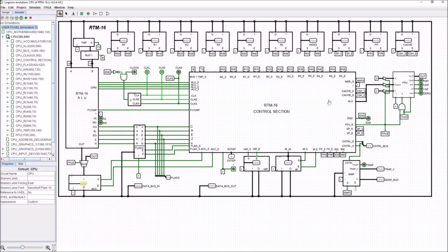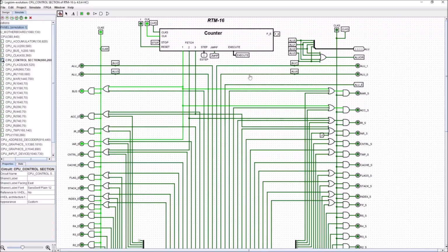So if we head into this and have a look at this ALU, the values that we're going to have here are going to be this value here. This is the ALU, so this is the select line for the floating point unit and CORDIC unit. And they're controlled by ALU 0, 1, 2 and 3. So here they are, ALU 0, 1, 2 and 3.